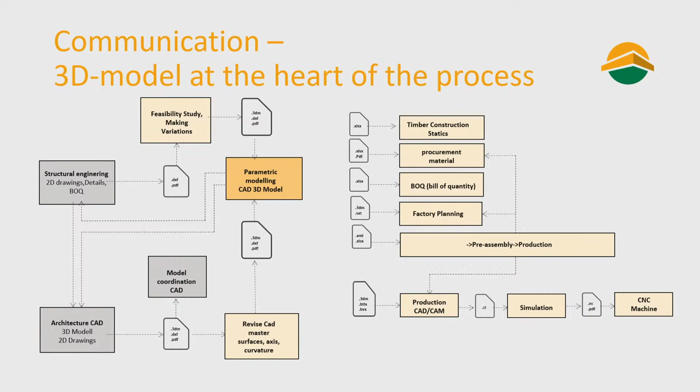On the other loop, we have the architecture cut. There, the coordination with all other disciplines is made. So coordination with the interface to concrete works, to disciplines like ventilation, electric, and so on. Also, this information is then implemented in the parametric model. And those loops need to turn several times to find really the final production geometry. And once we have this geometry, this coordination model, we start extracting information out of this model.